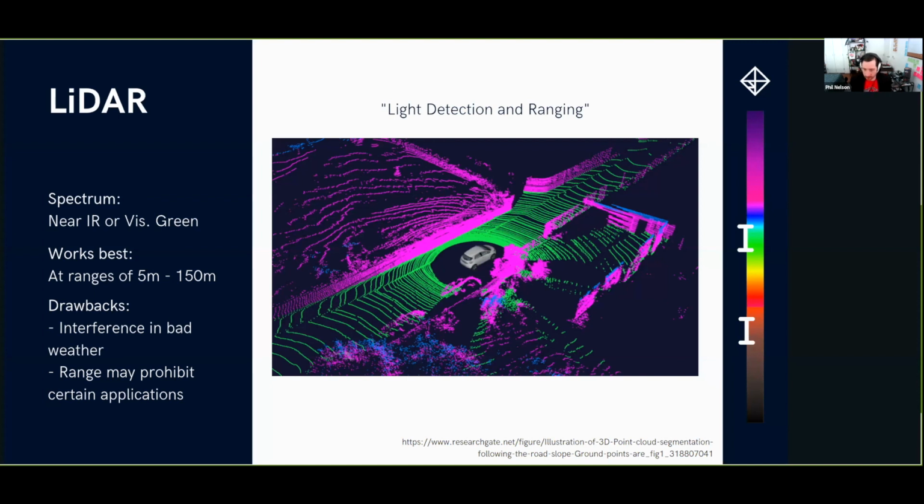But what I can tell you is that a single LiDAR does have points of failure. For instance, because of this focused beam of light, the shorter wavelength, you actually can read finer, smaller objects. But what this means is that the finer, smaller objects might be water particles in the air, right? It could be fog, it could be rain. And so if you're working outside, you could actually be getting the signature of rain in your LiDAR, which you don't want. It's not going to be helpful, right? So this interference of bad weather is something that autonomous cars, for instance, have to contend with, as well as anything outside working with a LiDAR.